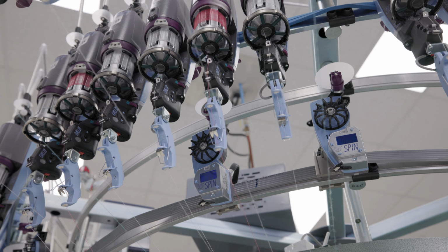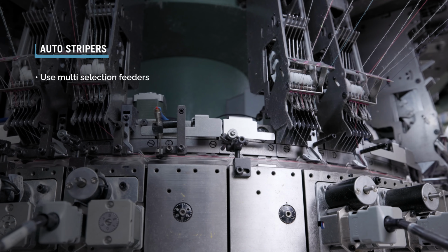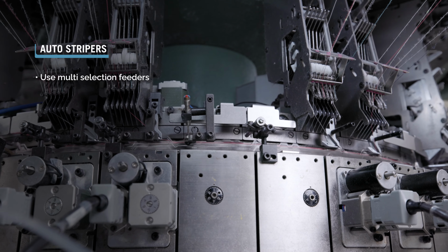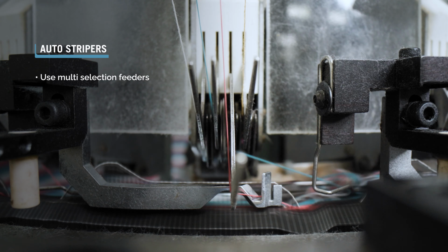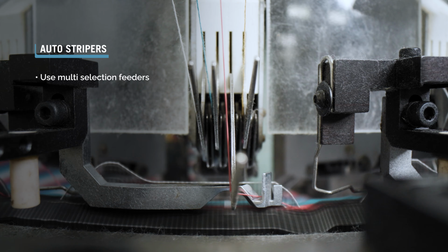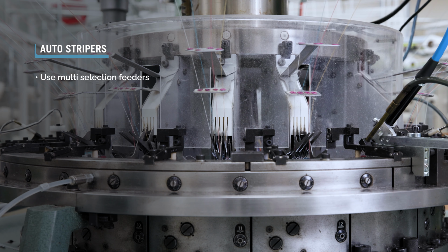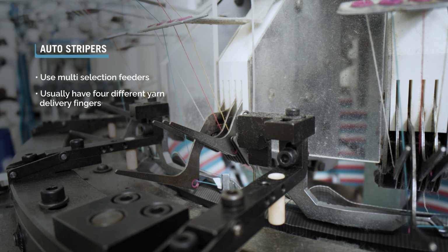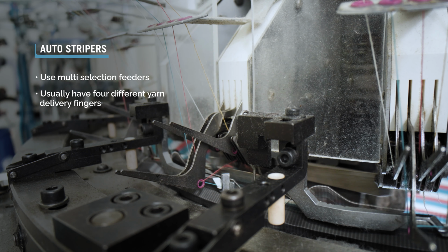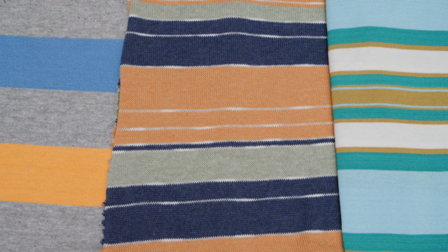When taller stripes are desired, the machinery must have auto-striper capability. Auto-stripers use multi-selection feeders, where the yarn being fed in at each feeder point can be changed at different points in the knitting cycle, allowing a stripe repeat taller than a single-cylinder rotation. Multi-feeders typically have 4 different yarn delivery fingers, providing the option for 4 different yarns or colors at each feeder point. Machines with multi-selection feeders can also create engineered stripes.